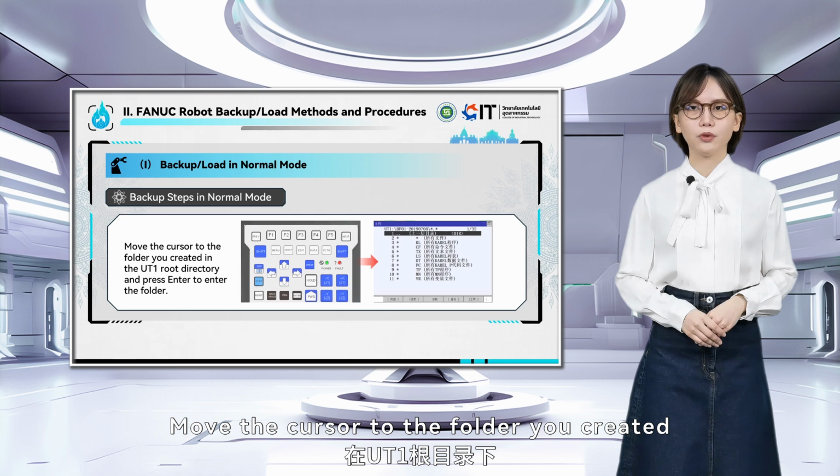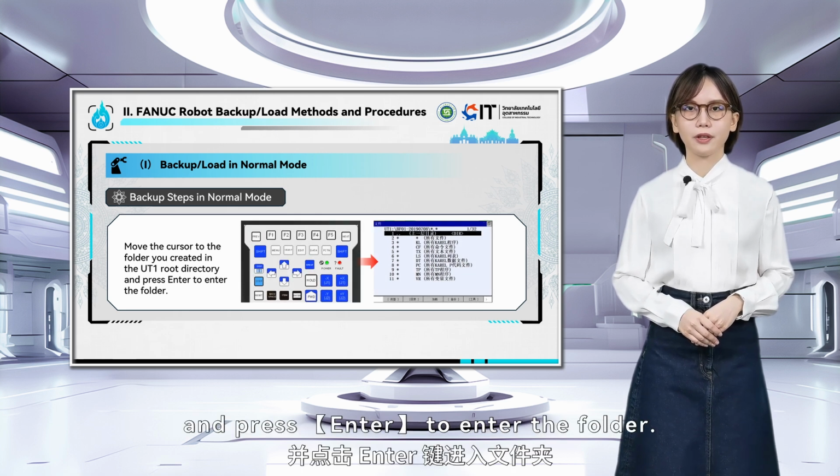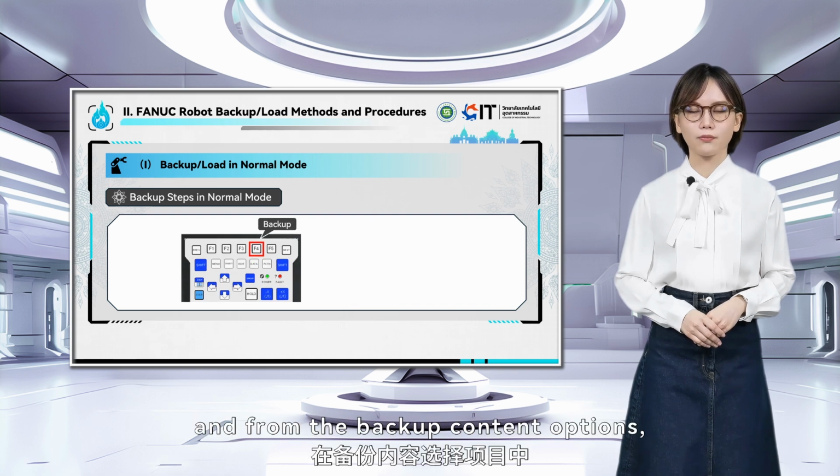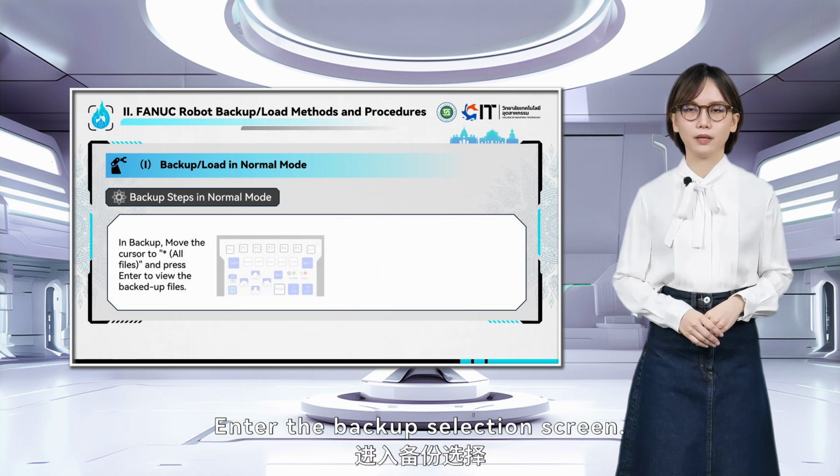Move the cursor to the folder you created in the UT1 root directory and press Enter to enter the folder. Press F for backup, and from the backup content options, select 2 TP programs. Enter the backup selection screen.